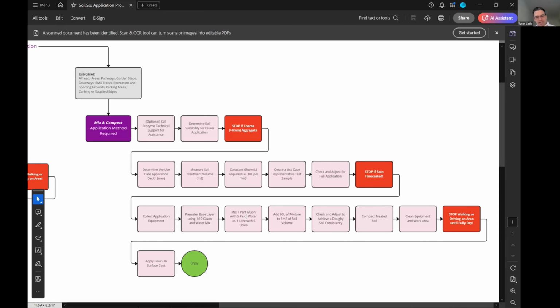And then when you compact it, it squeezes all the sand together and forces all the void spaces together, and the extra liquid, which seems too dry at that point. When you compact it, all that water squeezes out and it actually wets it off evenly. So it's a really good way to make sure that you can do it with just basic garden equipment. That's how I do it if I was DIY, if it wasn't too big an area.